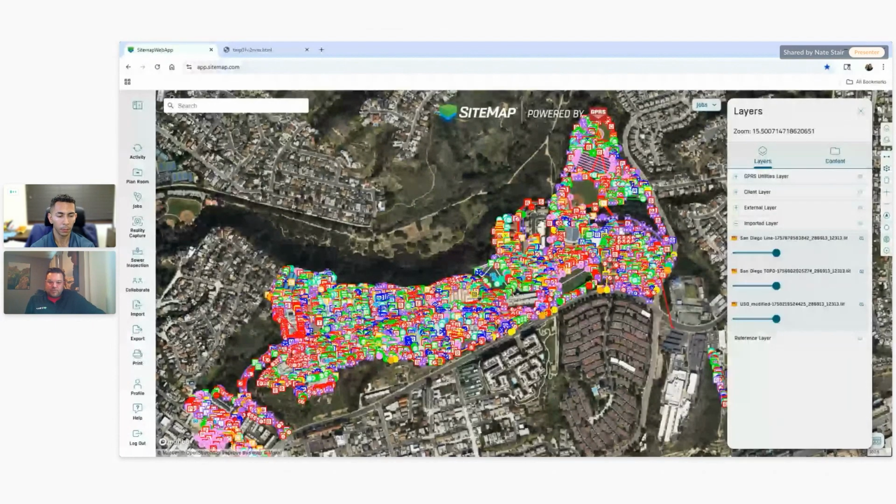Yeah. So I've been working here for almost 2 years in December, but when I first started, if there were any new projects going on, what we would tend to do is, if we see that there's going to be any infrastructure work going on outside the footprint of the building, we would typically consult either historical as-builts, which are either in CAD form or PDFs, or if the building was old enough, actual physical paper plans for when that project was first completed.